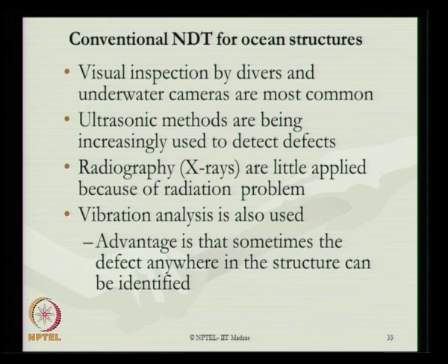Ultrasonic methods are being increasingly used to detect surface flaws and defects of the members. Radiography, what we call X-ray diffraction, is little applied because of the radiation problem when used underwater. Vibration analysis is becoming a very important technique which can also be used, because the advantage is that sometimes it detects defects in the structure in any location, which can be easily identified using this kind of analysis technique.